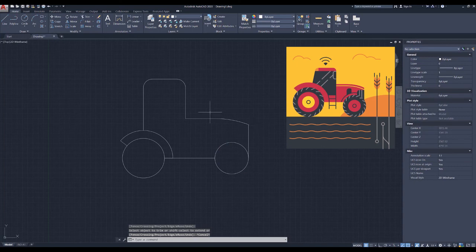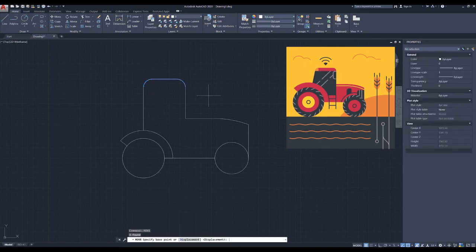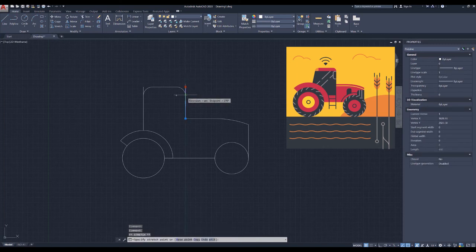That's starting to look really good. I'm actually noticing here that the cabin's looking quite tall. So what I might do is grab the top of my cabin using the blue pen to select only those lines that are within the box. And using the move function, I'm going to move this down a little bit. So you can see that I've got my tractor there. I'm going to move it down 100 mil, okay? Type in 100, press enter. Okay, and so now what you can do is amend the lines down to meet the node, all right?